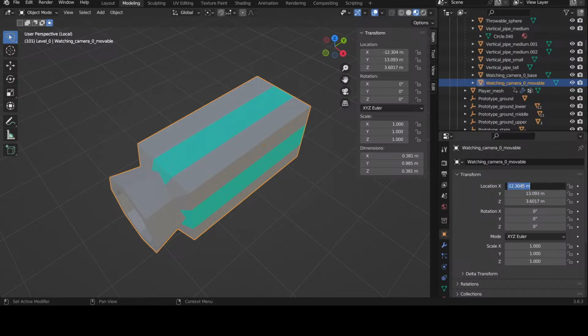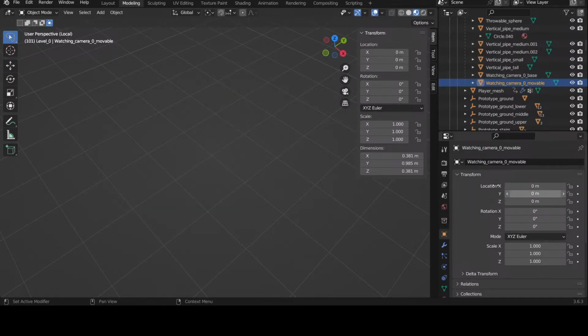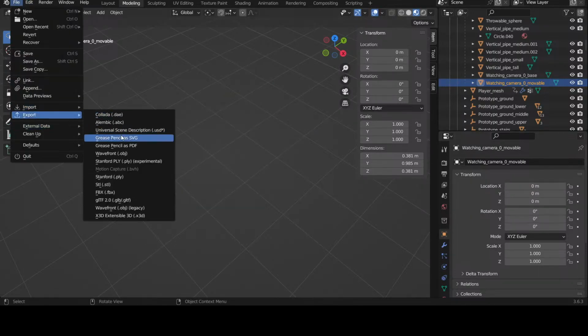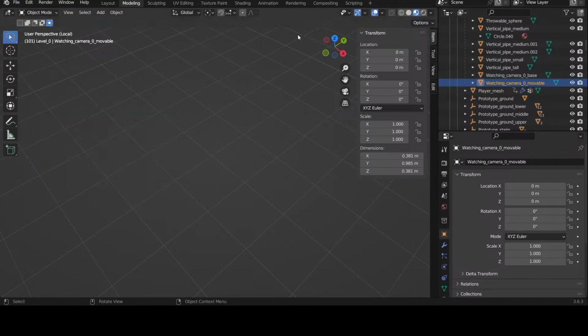So now important in my case is to make sure that when I export this to an OBJ file, which is the one I'm loading in my engine for my game, everything is set at the 000 coordinates. We triangulate the mesh, otherwise it will load the mesh with a displacement from the origin. So now we can put it.